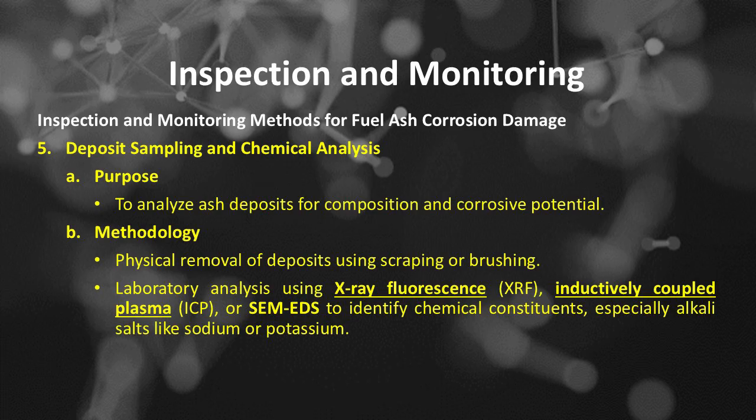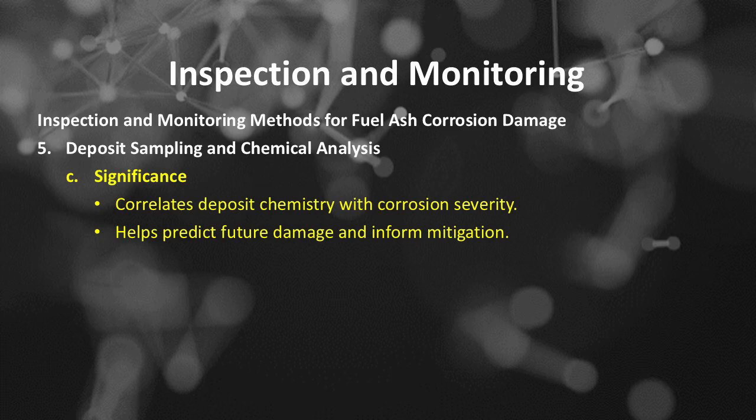Laboratory analysis using X-ray fluorescence, or XRF, inductively coupled plasma, or ICP, or SEM-EDS to identify chemical constituents, especially alkali salts like sodium or potassium. Number C. Significance. Correlates deposit chemistry with corrosion severity. Helps predict future damage and inform mitigation.